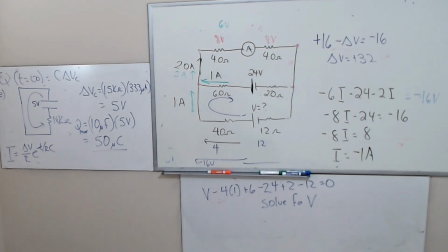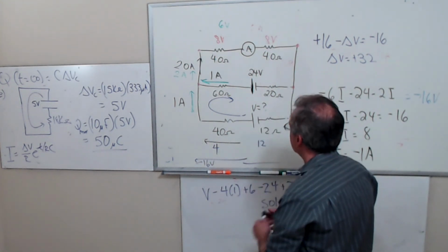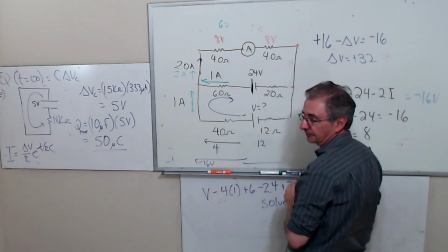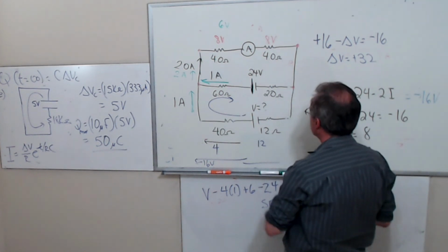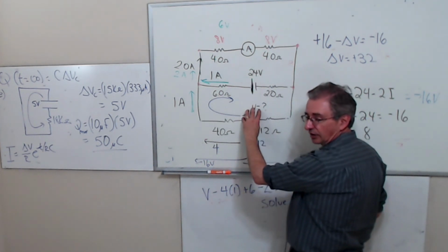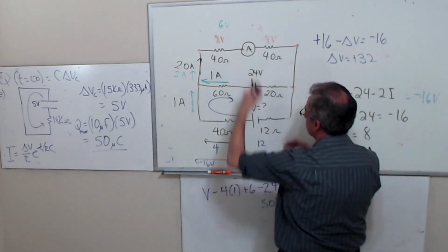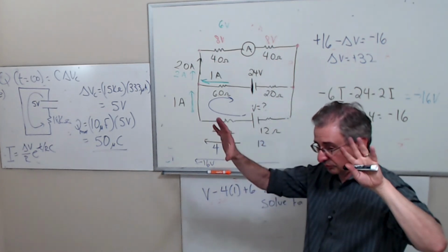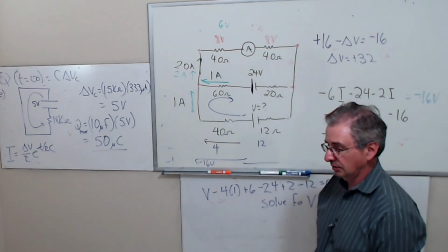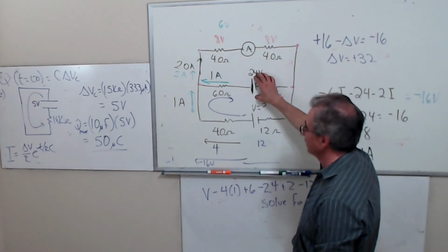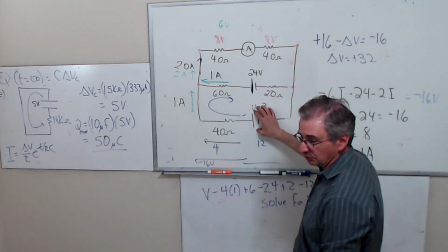For example, when you have a circuit with 2 power supplies, it all depends on how fast the method is. You can solve this problem by taking out this power supply and finding all your currents, then doing it again, putting this power supply back and getting rid of the other, and finding all the currents. Then the sum of the currents from the two different problems gives you your answer. It's called superposition.